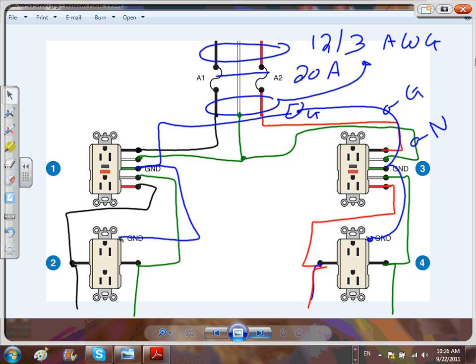And also, if you're replacing, Chris, you go to your mother-in-law and you're replacing her receptacles in her house that doesn't have a ground in it. Supposedly, they don't make a tamper resistant non-grounding receptacle. So you have to change it with, you don't have to put a tamper resistant receptacle. I disagree with this one because Tao, my friend, you know what you can do? You can change it with what? A GFCI tamper resistant, and that's okay.